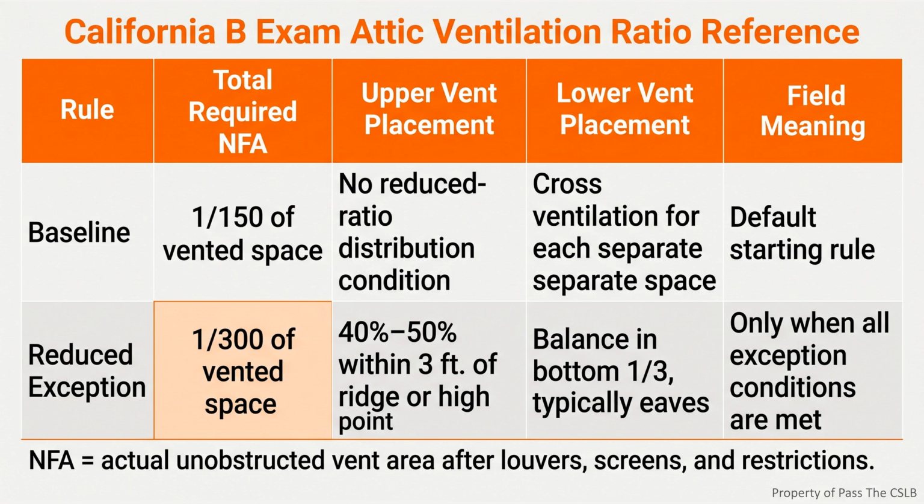Larger architectural openings need compliant corrosion-resistant backing that preserves that protection. In wildfire-prone locations, I also verify the applicable California ember-resistant vent requirements rather than assuming an ordinary screened vent is acceptable. The ratio tells me how much net free area is required. It does not prove that air can travel through the framing.